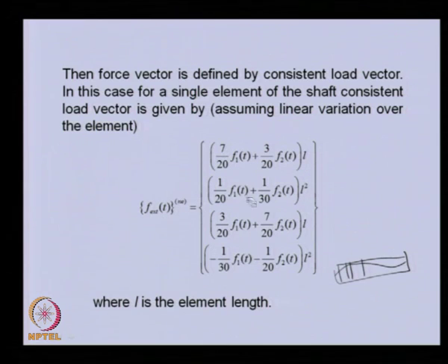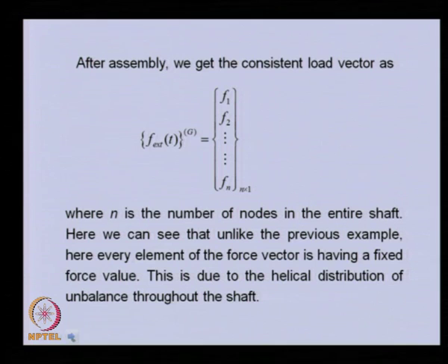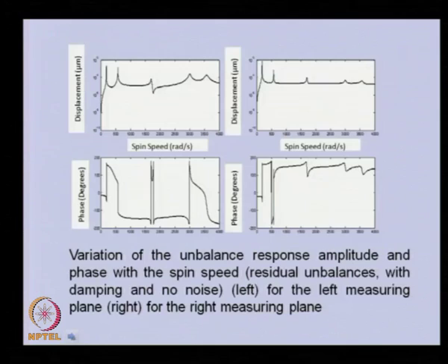This calculation of the consistent force factor we have shown when we discussed the FEM analysis of the transverse vibration, so I am not repeating this. This we directly used in the formulation for calculation of the unbalanced force because of the distributed eccentricity. In this particular case we will see that the distributed unbalance will be there in all the nodes, and this is the typical response.